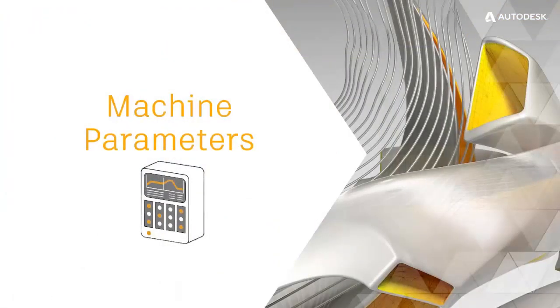The last topic on reducing cycle times I want to cover today is related to the processing variables we have on injection molding machines. As you'd expect, increasing or decreasing the melt temperature of a material will impact how long it takes for a part to cool. Likewise, if we increase or decrease the water inlet temperature from a thermolator, this will impact the overall cycle time. The difficult part here is how to measure or quantify these changes, and also how changing the process conditions affect other criteria, such as injection pressure, volumetric shrinkage, and warpage.